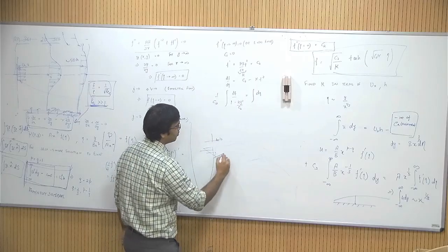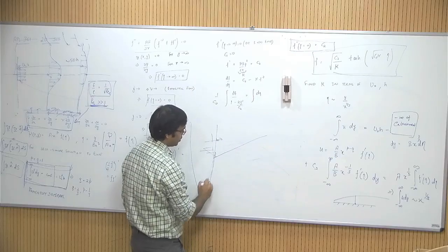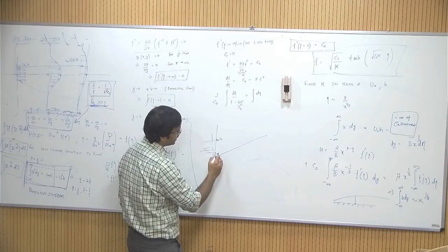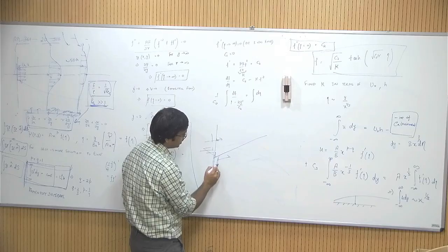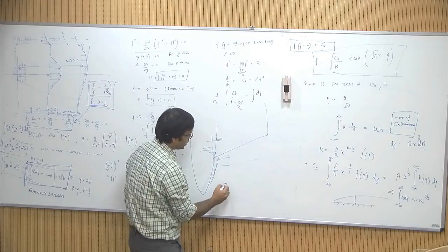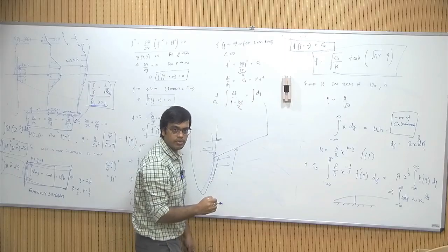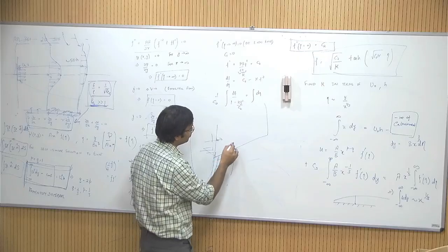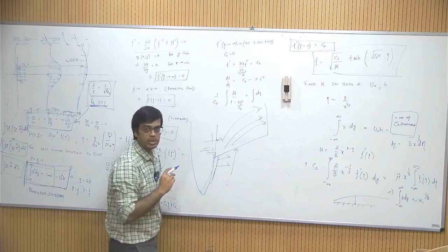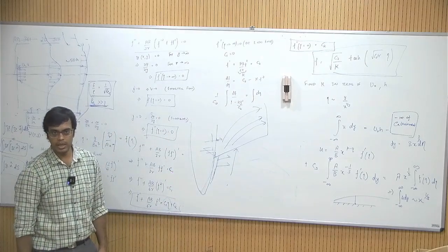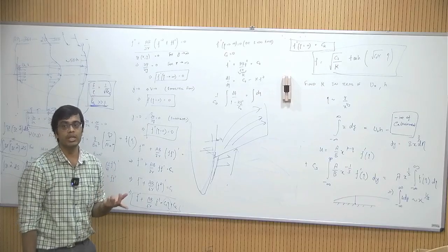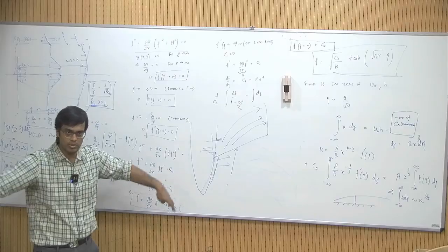Okay, this is where the wings start. Now what happens is, on the body of the airplane, on the fuselage, you have a boundary layer forming, which is causing a spanwise flow on the wing, and there is obviously a flow that is hitting the wing as well. So, the superposition of these gives you a spanwise flow as well as a downstream flow on the wings, and essentially on your wings you do not have 2D boundary layers, you have 3D boundary layers due to the spanwise flow caused by the fuselage.